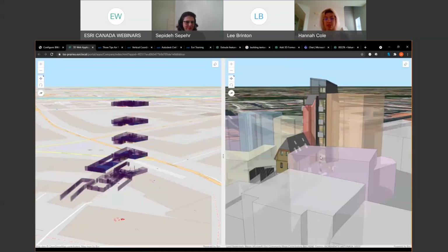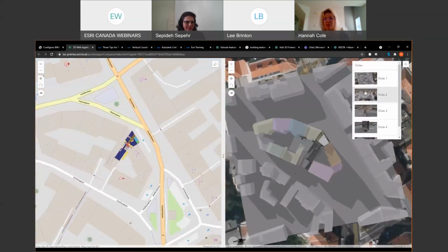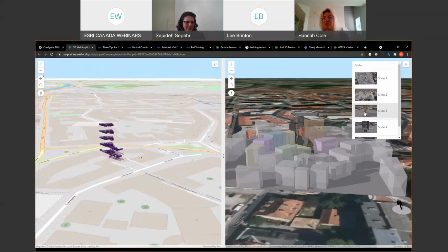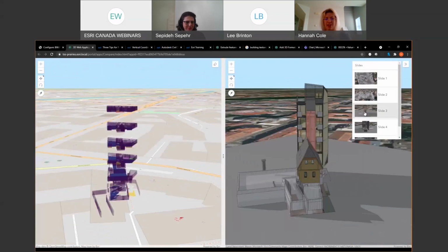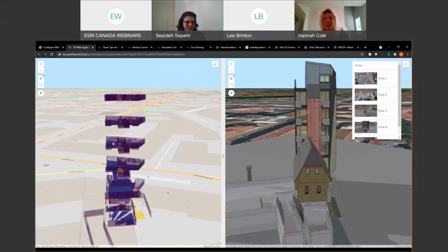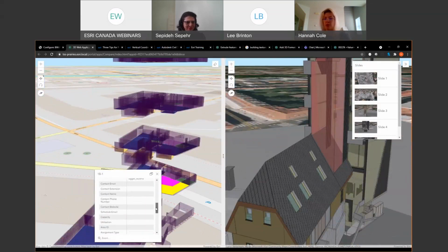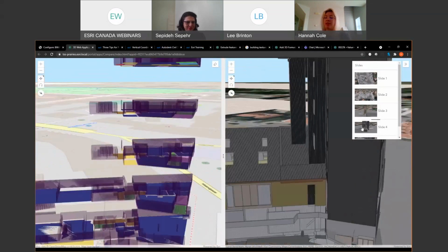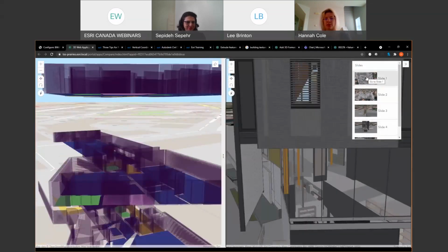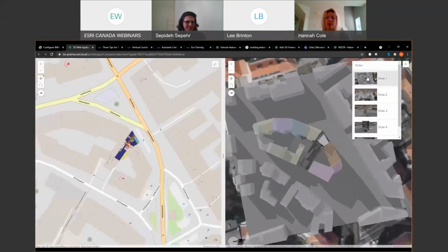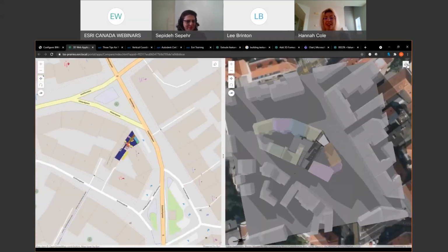in the same view. Note here that 3D layers obtained from Revit files can be visualized, queried, and interrogated in the same exact view as the GIS data, providing that they've been converted to a file geodatabase or shapefile format ahead of time and have coordinate system information that is compatible with your web scene. It's highly recommended that all GIS enthusiasts follow the Esri documentation for how to create 3D scenes using ArcGIS Pro and analyze this data and scene when publishing.